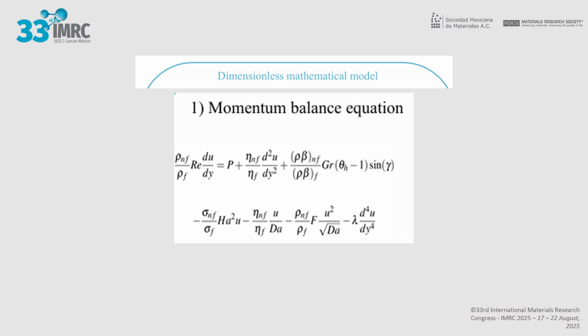Dimensionless mathematical model. This set of assumptions allows us to formulate the system of governing equations. Momentum balance equation. This equation describes how the different forces acting on the fluid affect its motion. Each term has a specific physical meaning. The most important for us is U, that is the dimensionless fluid velocity. Theta is the dimensionless temperature profile, and phi is the dimensionless nanoparticle concentration.